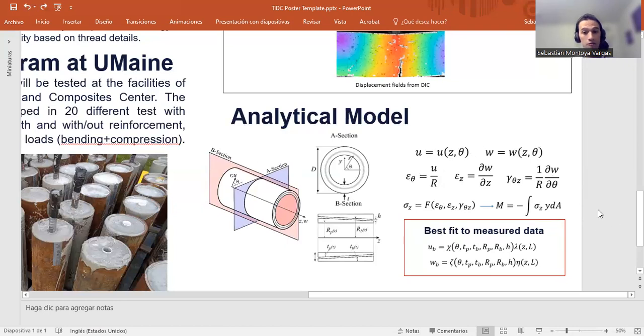The big question is, what are the displacements in a threaded connection? Because of the discontinuity presented by the threads, the deformation of this embedding no longer follows the Euler-Bernoulli assumption of plane sections remaining plane. So we have to come up with suitable functions that can tell you the distribution of this displacement over the cross section. That's where the DIC will play a big role.